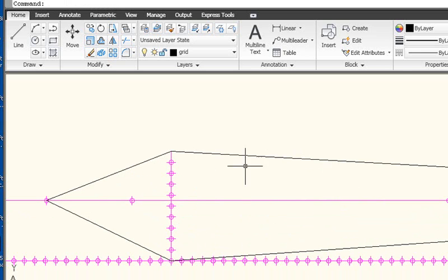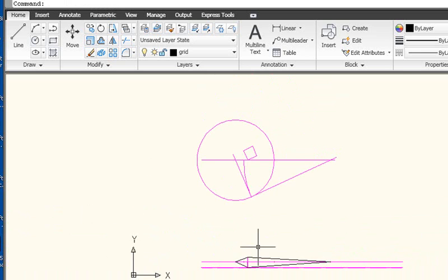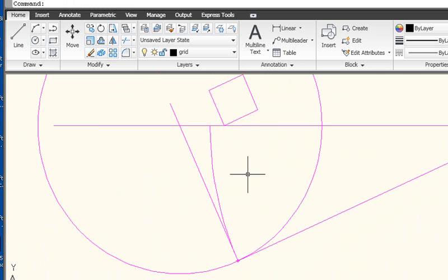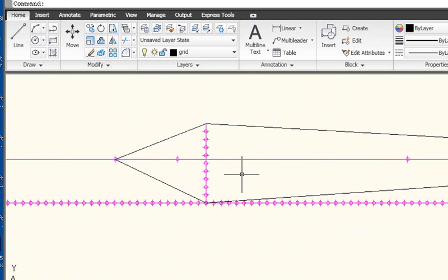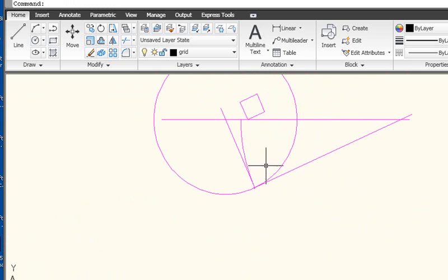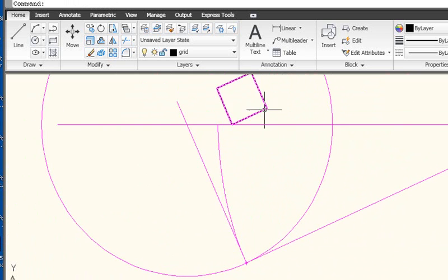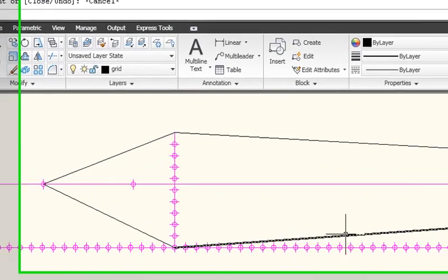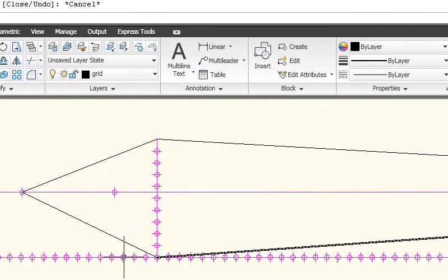So you see how prominently we're going to be able to see this side of the building, which matches our estimate here, since we put ourselves more across from the center of the building rather than at the corner. Alright, next we want to be able to figure out how far 10 feet is going to be in this direction. So that direction is actually being controlled by this baseline.